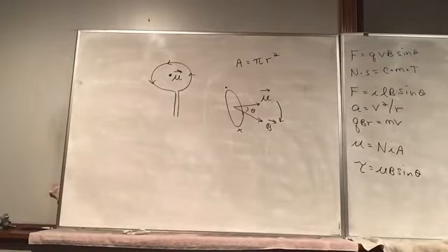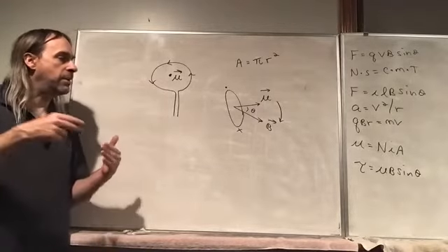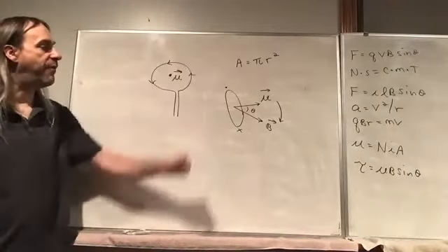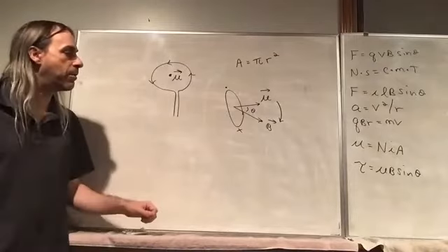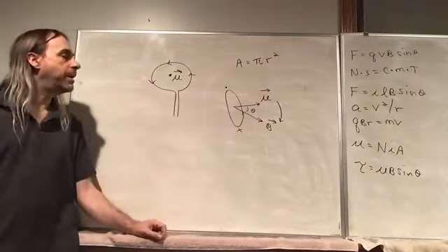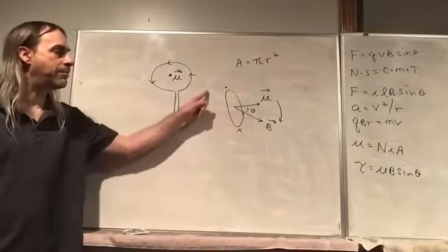We have one of these in lab where you can actually show it. We use the springs to create contact, so the current's always being fed on the same side of the coil. So it kind of automatically flips it around. But this wouldn't be a very good motor because the torque would vary a lot through its motion.